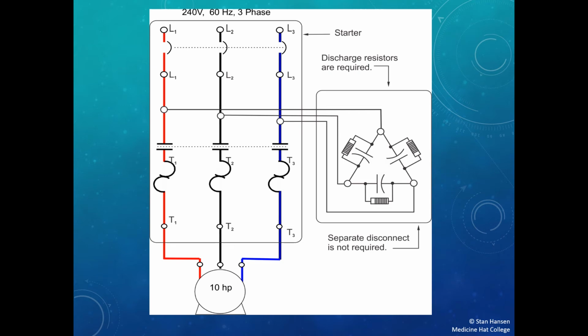In this case, the capacitors are still being protected by the motor disconnect switch, so they do not require their own separate disconnect, but since the overloads can disconnect the capacitors from the motor, we do require discharge resistors. The motor overloads are still based on the motor values of the full load amperage. Keep in mind, Rule 26.218 sub-rule 1 also applies here.